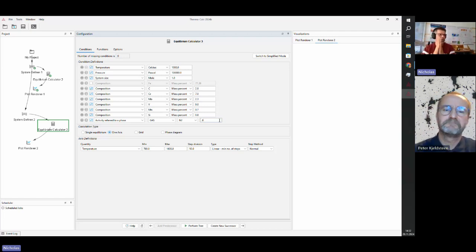And these calculations are realistic at high temperatures, because at high temperatures the gas phase is in equilibrium, you can say. And you can also assume that there's an equilibrium of nitrogen between the gas phase and the liquid metal, right? This is the condition of thermodynamic equilibrium, that activities of a certain element are the same in all phases. That's the definition of thermodynamic equilibrium.